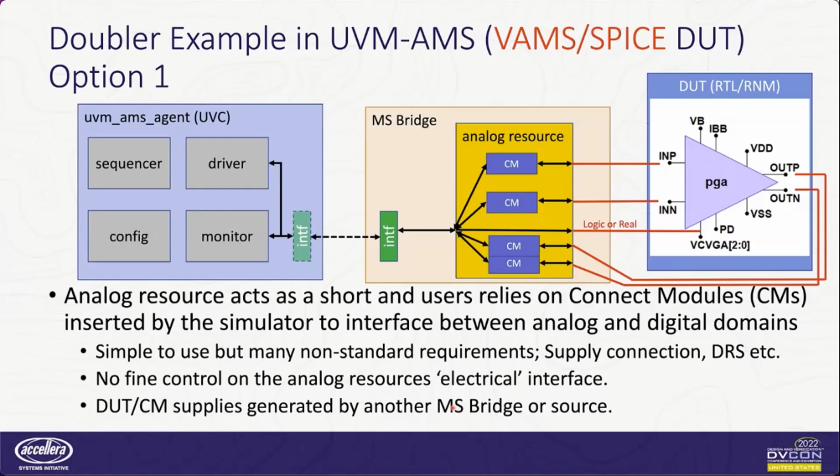So you can access the Verilog side to get the values that are being passed from the interface, and then you can assign that to a voltage and current to drive the electrical signals on the output ports or on the ports that are connected to the DUT.